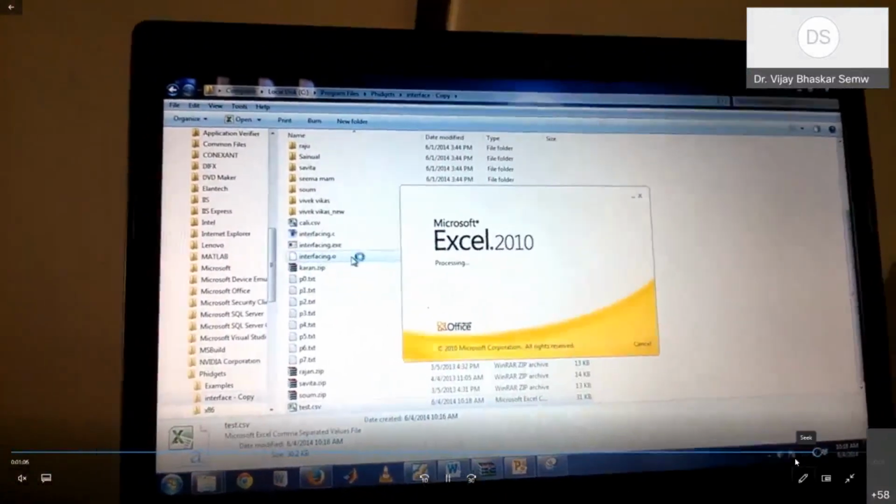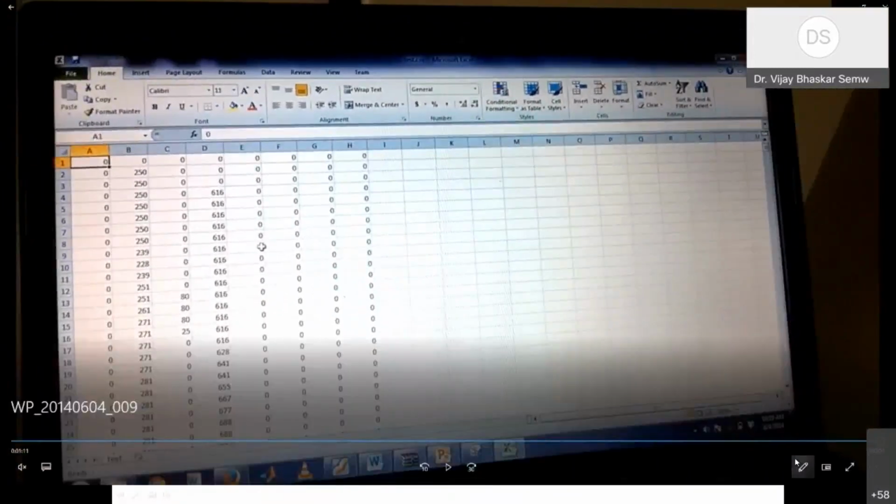The data you can see in the Excel sheet. And you can see that very sparse zeros are coming in this data. That means at that time these joints are not activated. So for this data, you have to apply pre-processing like data smoothing, where I'm not getting any data due to sensor error or something, because the potentiometers bound over the human joints are not that flexible. Somewhere you are getting constant values. So these kinds of issues will come when you are taking real sensor data.